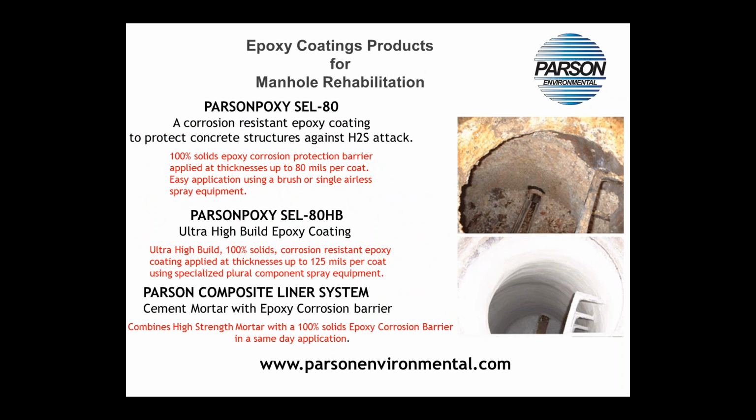Parson Epoxy SCL80 is a high-build, 100% solids epoxy coating used to achieve a high level of corrosion protection, which could be in the area of a pH of less than 1. The product can be brush or spray applied up to 80 mils thick in a single coat. Parson Epoxy SCL80 HB is an ultra-high build, 100% solids epoxy coating with application thicknesses that can reach 125 mils or 1/8 of an inch per coat. It can also be brush or spray applied.